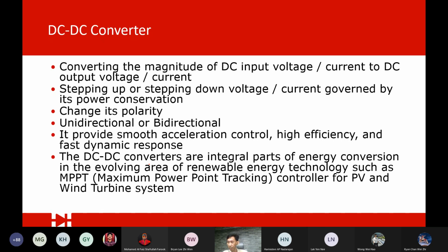The DC-DC side converts your panel voltage, because the panel voltage and current change when the sun irradiance changes. So the DC-DC makes sure that whatever changes, your output remains constant. The 400 watts at the DC link has to be constant for the DC-AC, so that you can inject the power to the grid in a much steadier manner.